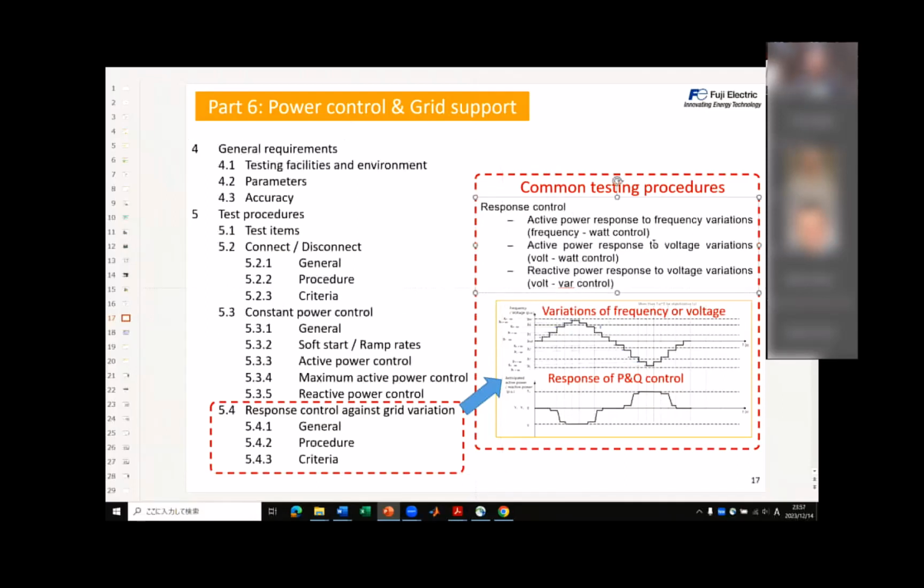When we manage the frequency variations, PV inverters can control the injection of active power. And like a STATCOM, if the PCE or PV inverters detect the voltage fluctuation at the terminal, in order to reduce such a deviation, the PCE can manage the reactive power control. It is a very simple autonomous control.